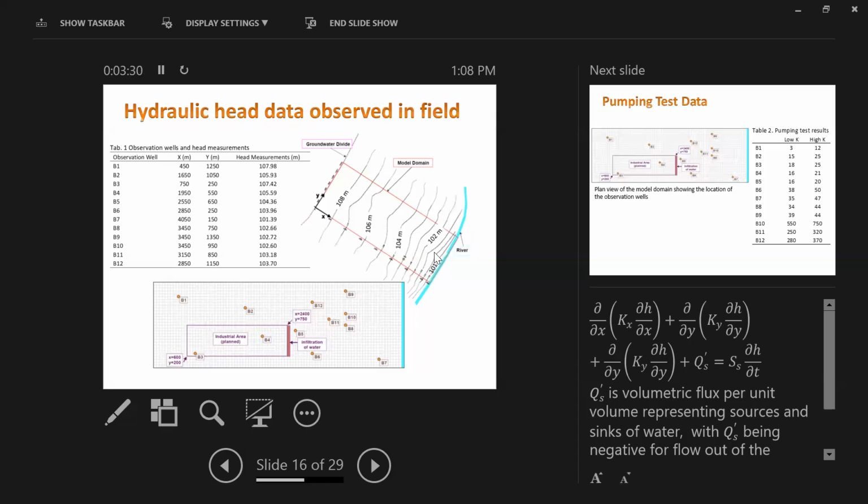We'll just add it to the model, because initially this is the pre-development, so pumping is equal to zero, we are not pumping anything. And the recharge that was given, I think, as 0.0008 meter per day, for example. Here, pumping is in meter cube per day, so here we are giving 0 meter cube per day. This will depend on that.